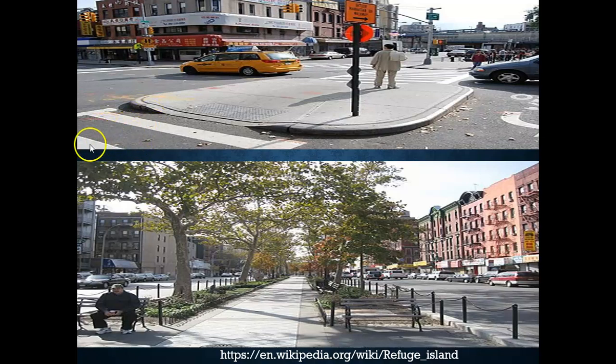From here we can see the sign of a pedestrian crossing, which shows that there has been a movement from one side of the road crossing to this point where you can see this man standing and waiting to cross to the other side. As a result of the fact that the road is too long for pedestrians to cross at once, there is a need to have a refuge island where pedestrians can cross, wait a while before crossing the road to the other side. And this position on the road is what we call the refuge island or pedestrian refuge or pedestrian island. It's just a small section on the roadway or sidewalk.